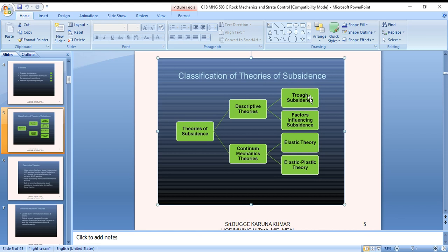Surface subsidence, manifested by vertical and lateral surface displacement, usually occurs almost immediately following the first indication of the subsurface subsidence. These displacements produce a lateral surface strain that in some instances increases the dimension of the excavation, and with time, surface cracks are produced.